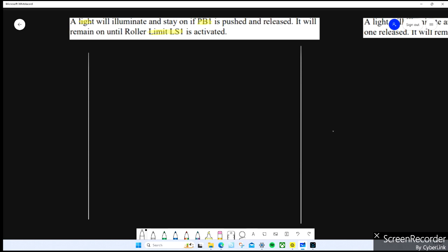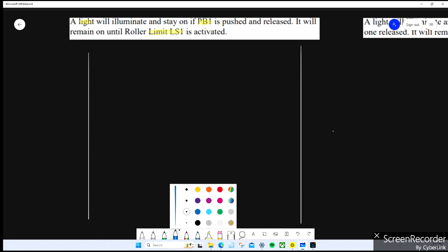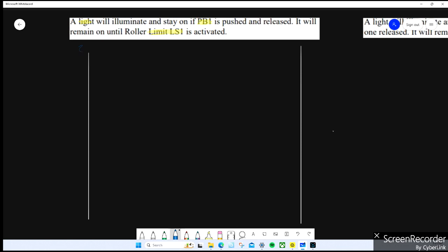Now in our control circuit, it could be various voltages. Typically, the ones I work on and design are 24 volt DC, and that doesn't show up very well, so I'm going to switch colors. Here we go. 24 volt DC. And then this would be my DC COM for common, or you could also call it 0 volts DC, right? Basically, I have 24 volts of potential from this side to this side. You could see control circuits that are also 120 volts AC, right? So when you work with these controls, pay attention to the voltage. On a good system that follows some standards, when you see blue, that's typically showing you it's a 24 volt system. And when you see red, it's 120 volts. Don't assume it though. Always use your meter. Check the voltage and verify that.